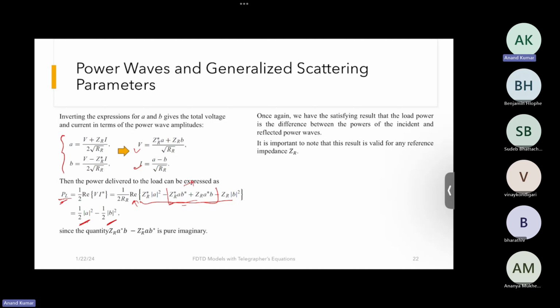So we are getting the same conclusion, but over here we do not have the same restriction, because we have now included the impedance values, and it could be real or imaginary. So this result is more conclusive than the previous result that we got. And we have also removed the dependence on having a transmission line, so we can calculate this against any reference impedance.